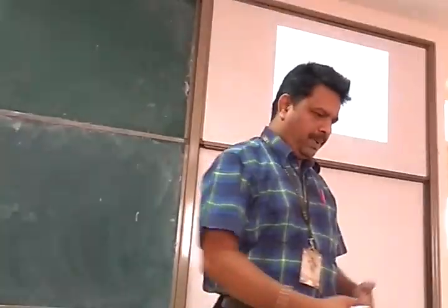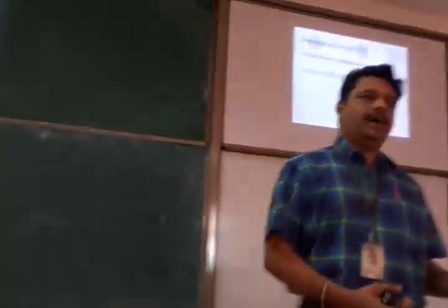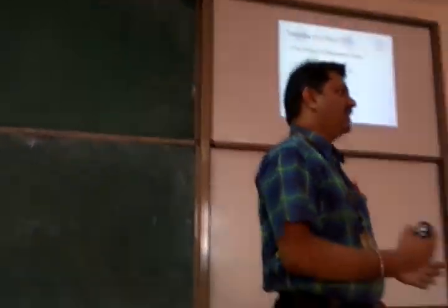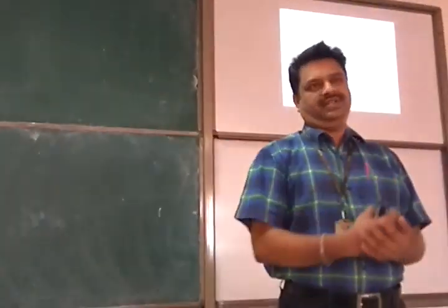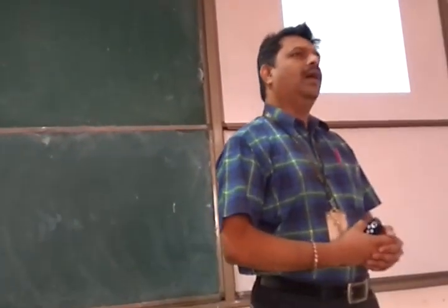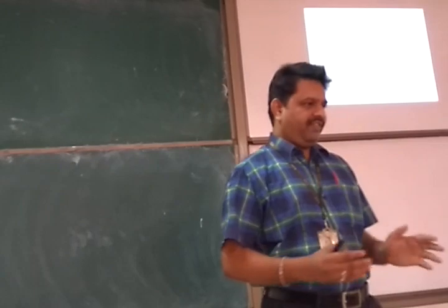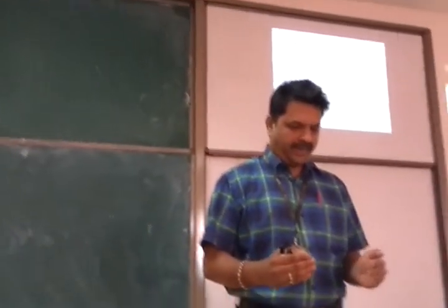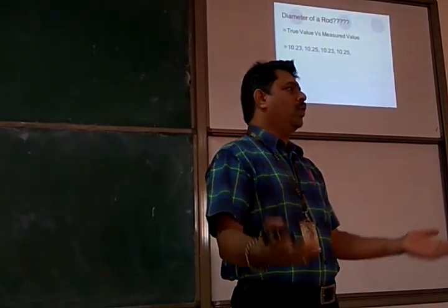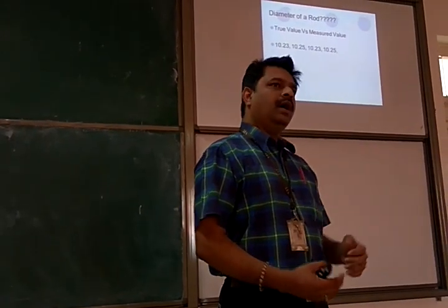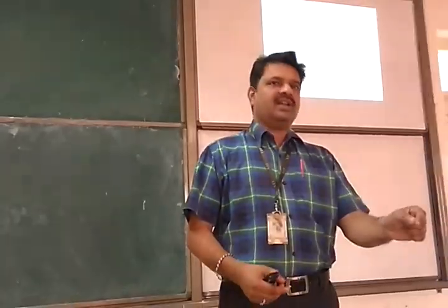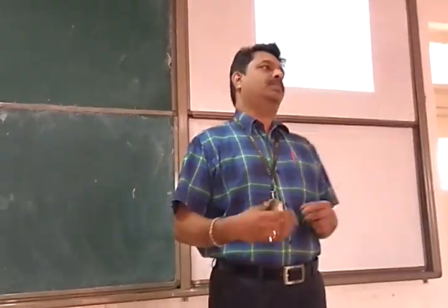Next couple of minutes, we'll be talking about the propagation of error, quantification and propagation. Those are the two things. What is meant by propagation? If I am computing some parameter based on 2 or more measurements, then how each one of the errors affects the final result is propagation.